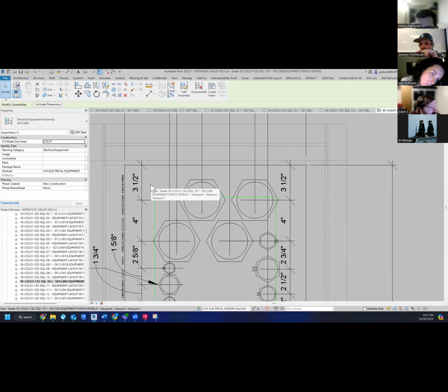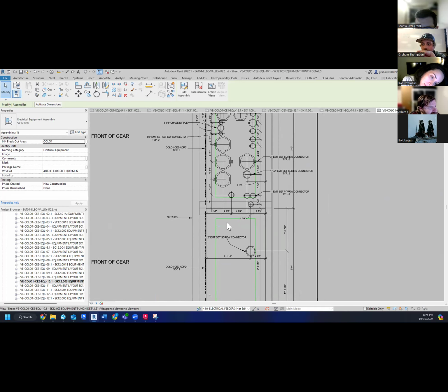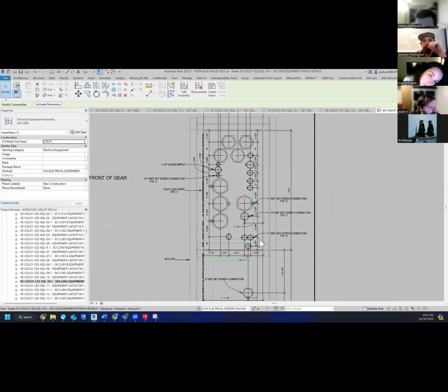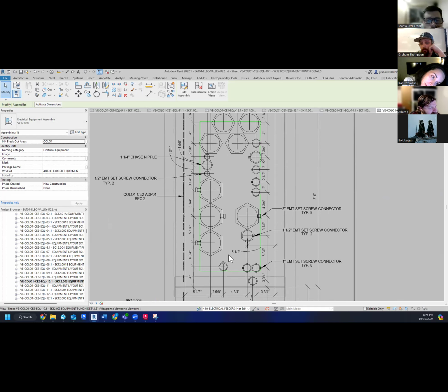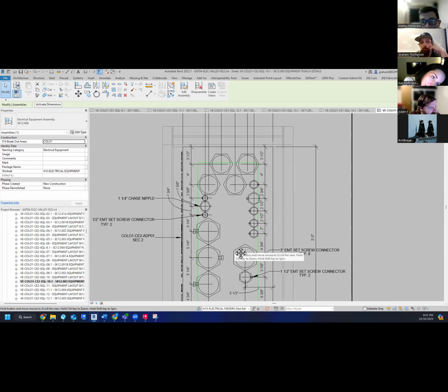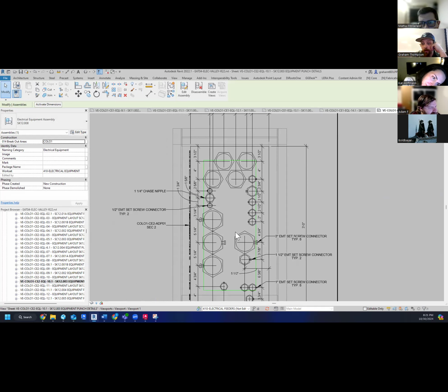It's a 3-inch piece of angle iron that's making the framework for all these pieces of switch gear. So they've got this framework inside of them, and they're wrapped with sheet metal essentially. But you can't drill through that. If you do, you've got a hole and connector structural damage to it, and you will not get an inspector to pass it. So you've just wasted time and thousands of dollars, just because you were a quarter inch off.